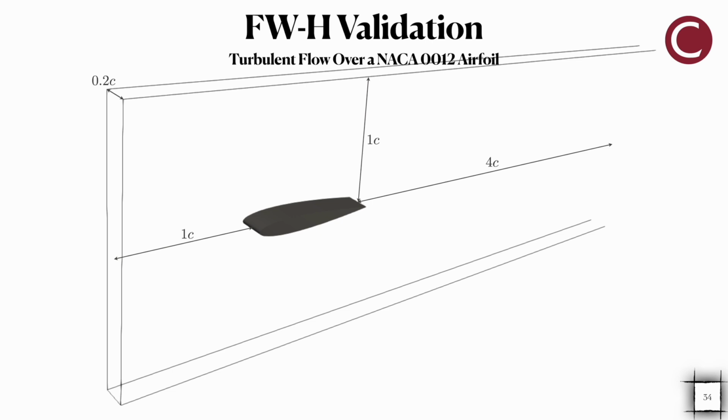And here we have the data surface that we used in the CFD simulation. And we gathered the flow field data on this data surface and used it as input to the Ffowcs Williams and Hawkings solver, the acoustic solver.